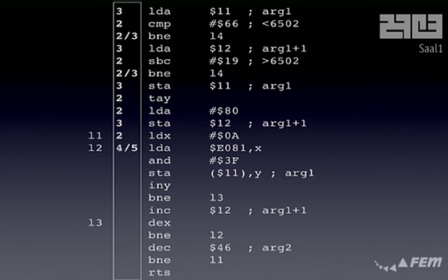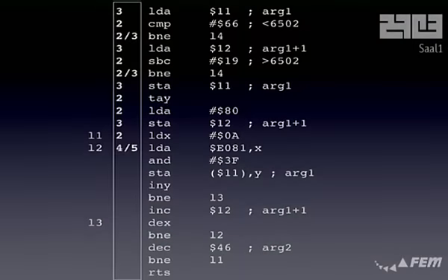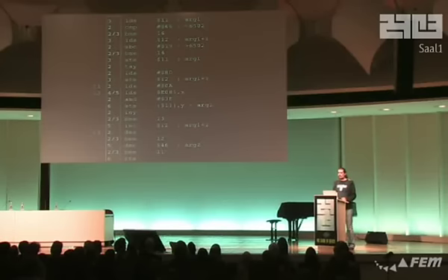Then this one is interesting. The load, the operand 1, operand 2, that's 3 fetches already. Then the actual fetch from memory, so that's 4. But in case we have an overflow, in case we have a carry into the next page in here, then the ALU has to do 1 extra step, so that's 5 cycles. And let's go through all these real quick. So 6 for something more complicated. An increment of 0 page is 5. And what can really kill performance is an RTS, or a jump to subroutine, and an RTS in combination are already 12 cycles that you're wasting right there.